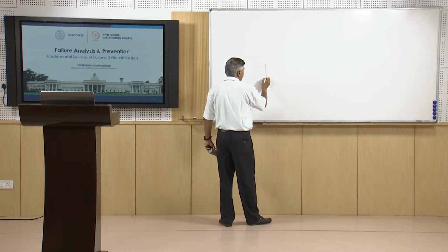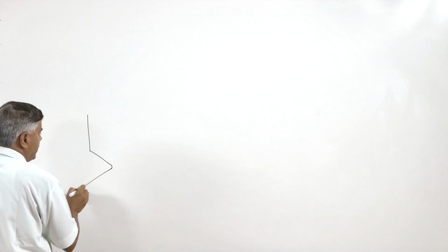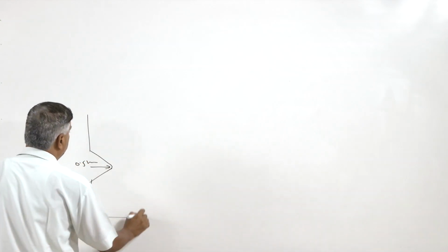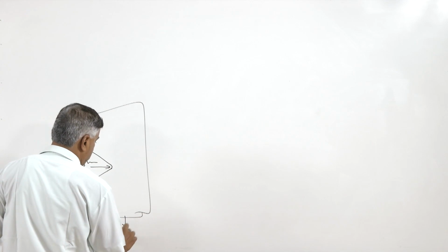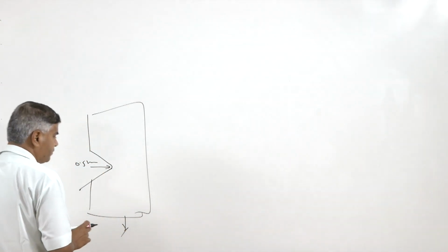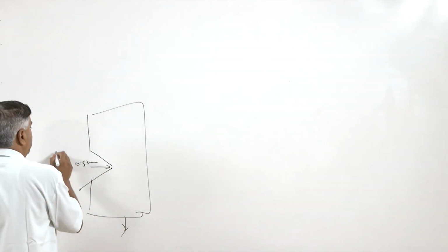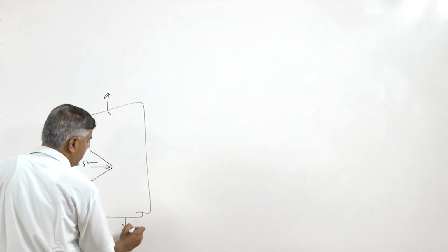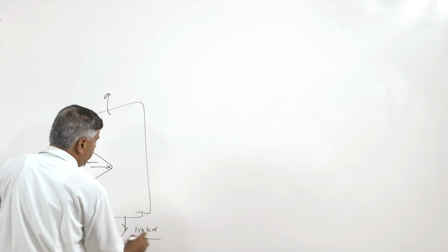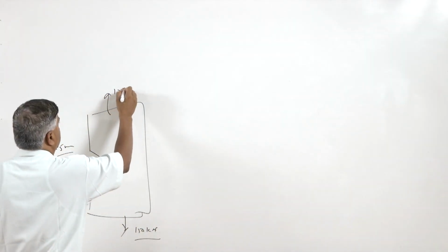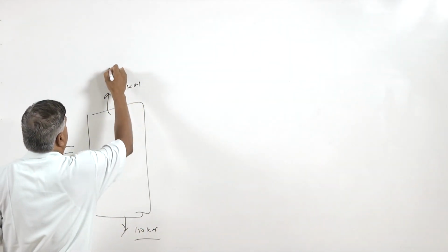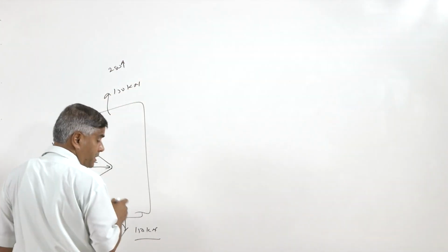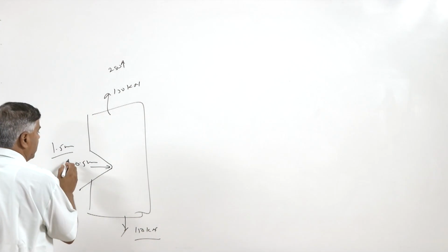Say for example, if there was a notch with the radius of say 0.5 mm, this will be causing the more severe stress conditions as compared to the case when it had say 1.5. So, under the low load conditions like 150 kilonewton it may be okay, but if the load magnitude is increased to 250 kilonewton, then these stress raisers may become more crucial,